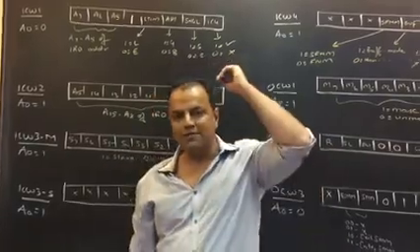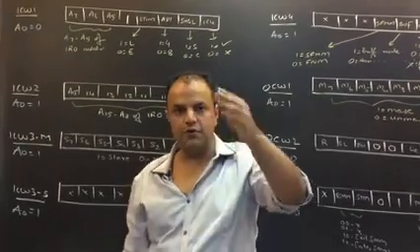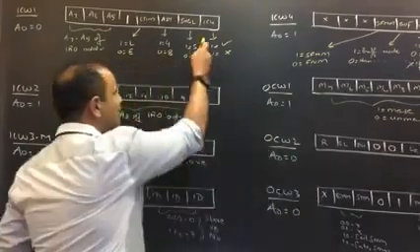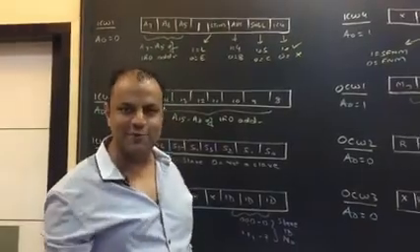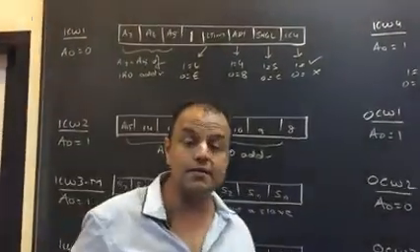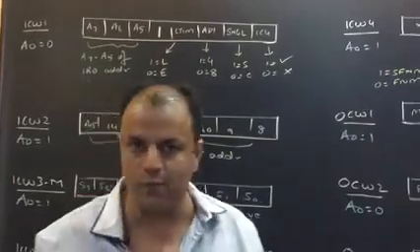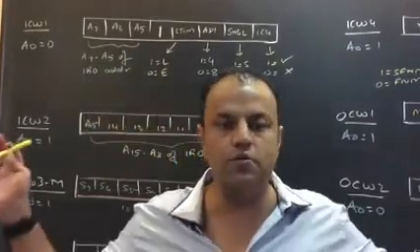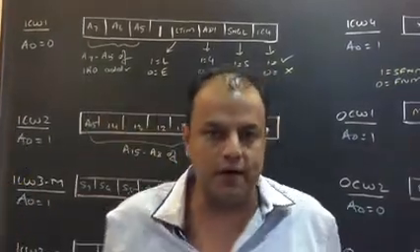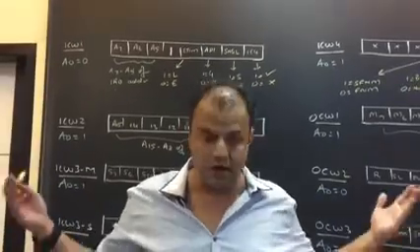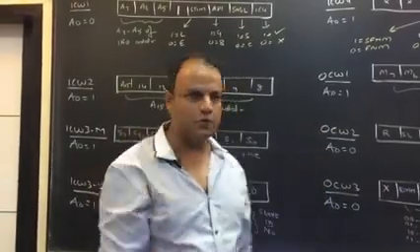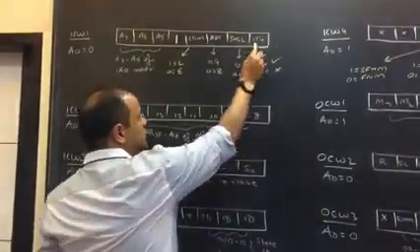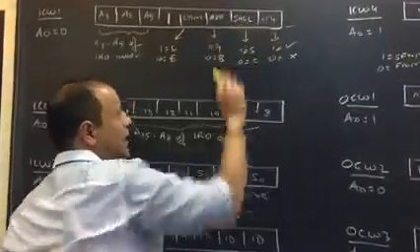Whatever is the name of the bit, that is 1, and 0 is the opposite of that. The bit is called IC4. Now, 1 means ICW4 is required, 0 means it's not required. If you learn things like this, you will not have to mug up what happens on 1 and 0. All you need to do is remember these patterns. There's no way around it. But if you understand it, remembering the patterns becomes easy. Once you remember the pattern, the 1s and the 0s will follow automatically. Anyway, so that is IC4.